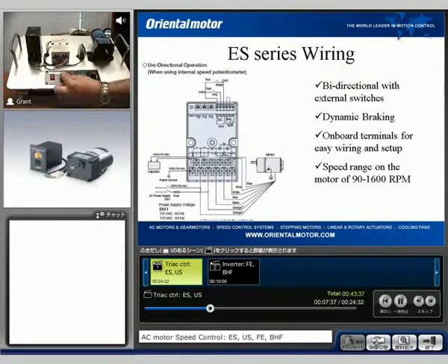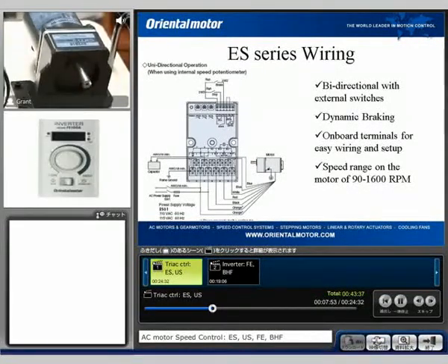So I'm going to go ahead and turn on the unit. Now you can see, I'll give you a better close-up look of the motor. Now I can control this speed via an internal or external potentiometer. So I'm going to slow it down with the external pot. Now this does have a 15:1 gear ratio on the motor, so the output speed will be a bit slower. And again, at any time during this presentation, feel free to type in any question you may have.